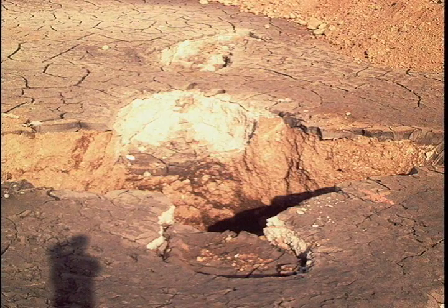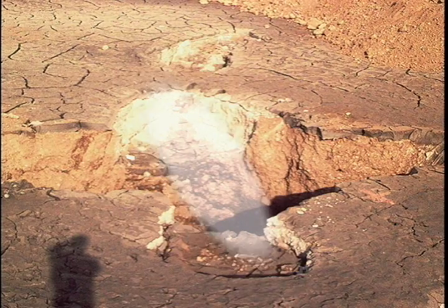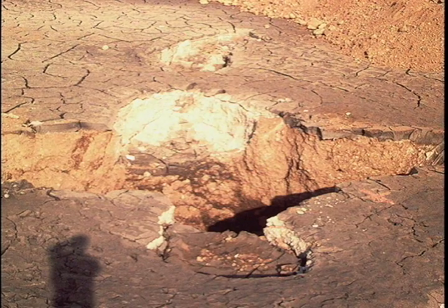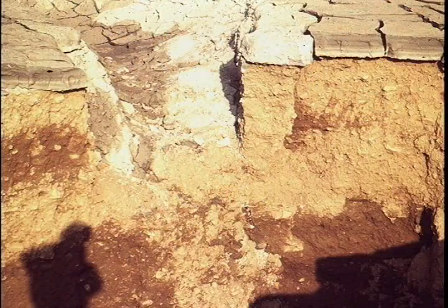This photograph shows an elongated sinkhole following a presumed tension crack. A backhoe trench has been dug across the sinkhole. The layer of silt which was deposited while the reservoir was up is evident. In the dried out state, the silt has a gray color. Another example of an elongated sinkhole is shown in the next photograph. In this instance, there seems to have been a branching of the tension cracks. Here is a photograph of a deep exploratory trench across the previous sinkhole.